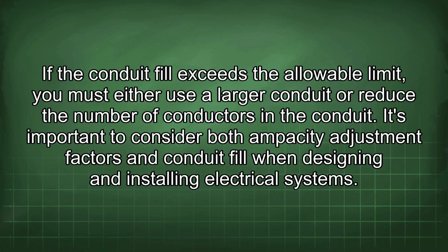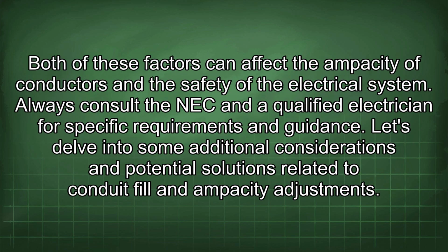conductors in the conduit. It's important to consider both ampacity adjustment factors and conduit fill when designing and installing electrical systems. Both of these factors can affect the ampacity of conductors and the safety of the electrical system. Always consult the NEC and a qualified electrician for specific requirements and guidance.